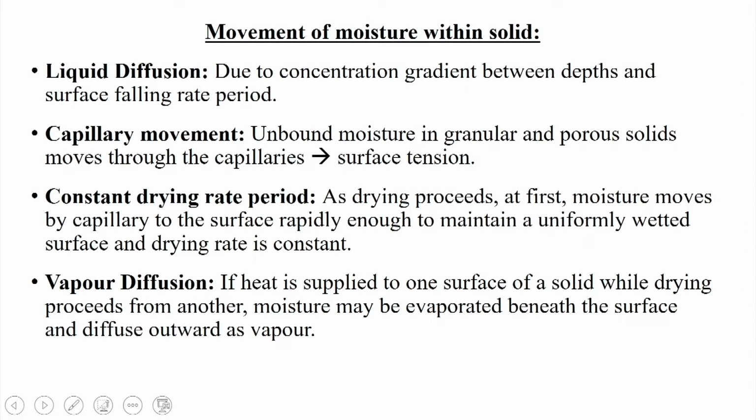The first movement is liquid diffusion, due to the concentration gradient between depths and the surface; in the falling rate period, the liquid diffusion takes place. Another movement is capillary movement: unbound moisture in granular and porous solids moves through the capillaries, and this is due to surface tension only.